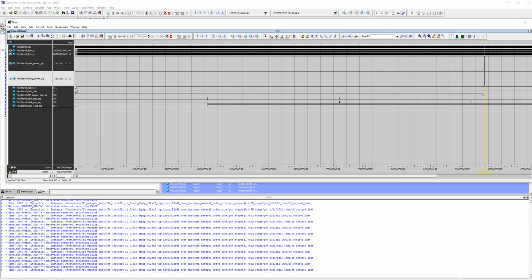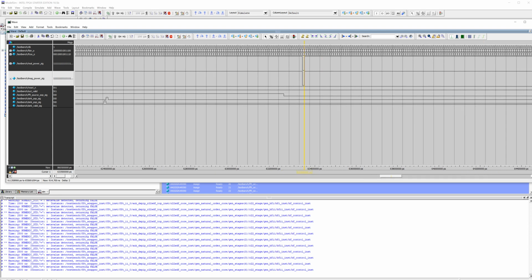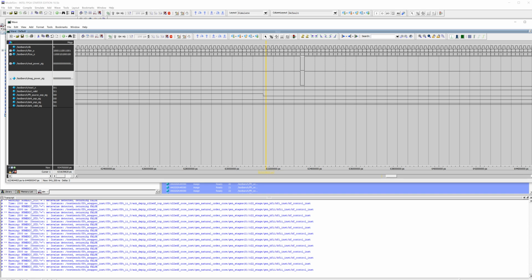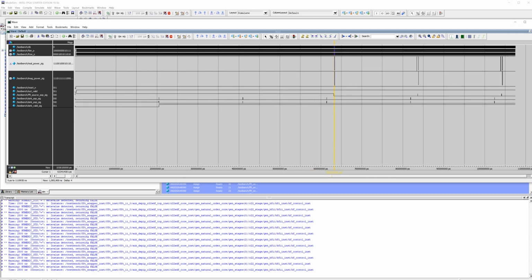So I'll just zoom in on the cursor here, and if this is the start of packet, you can see around about bin 10 we have the spike, and that's exactly what we expected. We'll just let it run a bit and we see the same thing repeated. So that spike corresponds to the 390 kilohertz signal. This, we can say, is working as it should be.